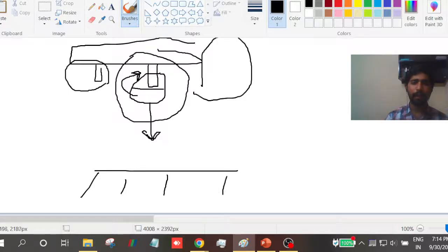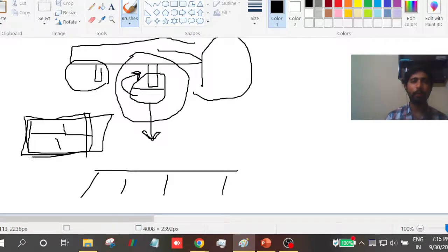Okay, so when it is falling, it has partially filled fuel, say. So what happens is that due to this fluid structure interaction, it is actually computational multi-fluid structure interaction, because you have air, you have water, and then you have a structure also surrounding it. Okay, so due to the wobbling motion, it might change the force which is acting on the structure, and it might lead to this drop tank falling on a different place altogether. So we need to ensure that the geometry is very rigid, in a way that it does not get influenced by the forces acting due to the wobbling motion of fuel inside this drop tank.